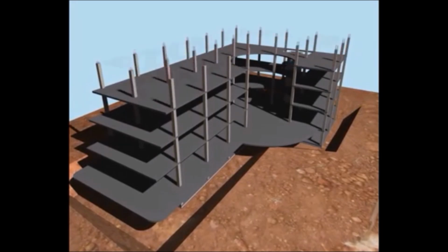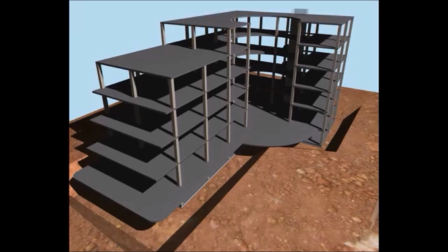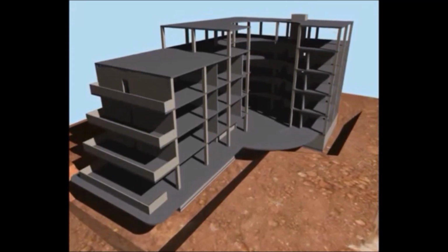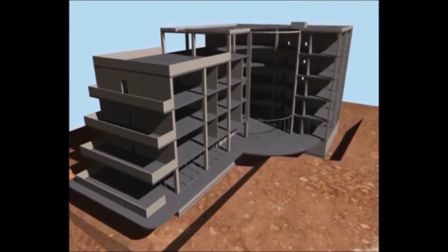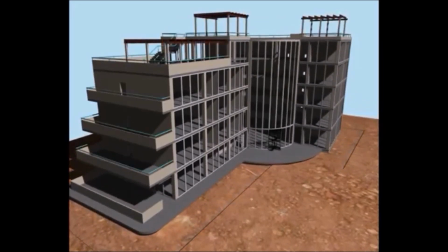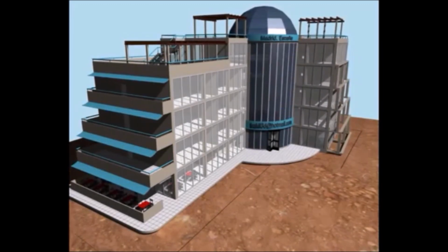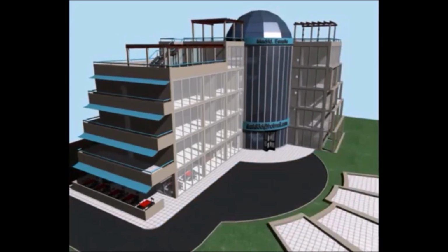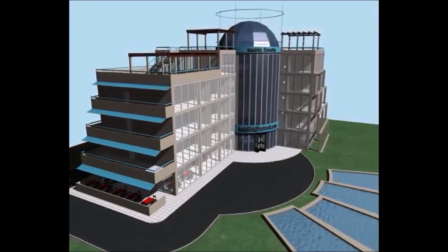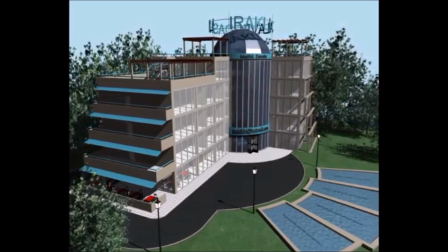If the beam is not connected firmly to the slab, then the slab transfers all of its weight to the beam and the slab contributes nothing to the load carrying capacity of the beam. However, if the slab is connected positively to the beam with studs, then a portion of the slab can be assumed to act compositely with the beam. In effect, this composite creates a larger and stronger beam than would be provided by the steel beam alone. The structural engineer may calculate a transformed section as one step in analyzing the load carrying capacity of the composite beam.